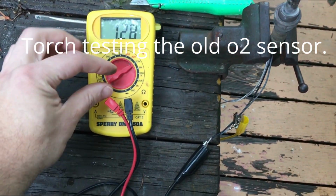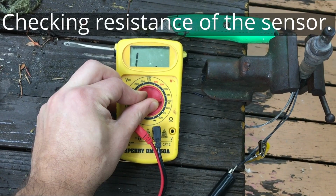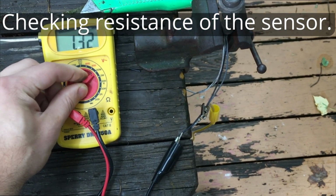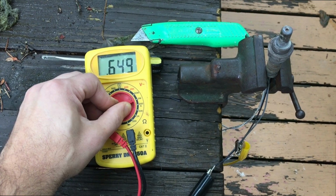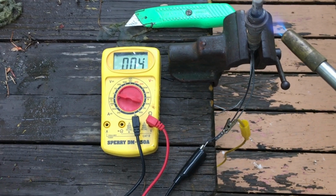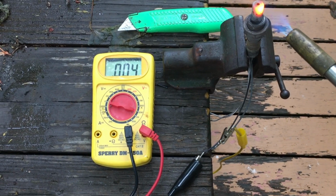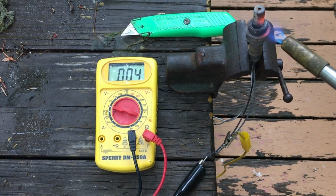Before I end this video, I'm also going to do a torch test of the old oxygen sensor. What I'm doing here is measuring the continuity of the sensor, and there does seem to be some continuity on the more sensitive ranges of the ohm meter. After I do that, I start the actual torch test, and there are more in-depth videos online about how to do this. I basically connected the gray and black wire to the voltmeter, because generally speaking, the white wires are for the heater element and the black and gray wires carry the signal.